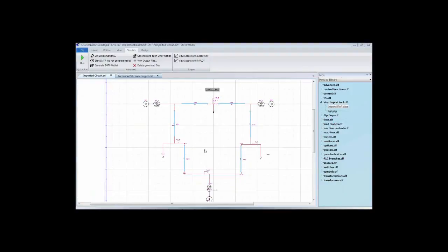And for instance, let's say that we use ETAP for short circuit and for selectivity analysis. But now we want to perform a capacitor bank analysis. We want to check the overvoltage that we'll have on this bus when I'm connecting a large capacitor bank, and we want to make sure that the equipment connected to this bus is correctly sized.